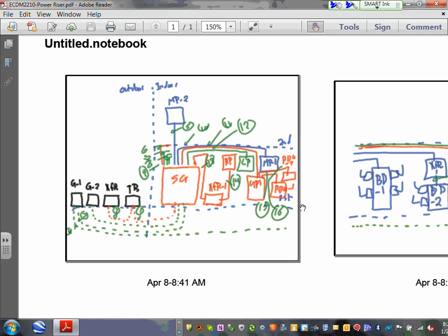How many sections do I need? 3 sections. You need 3 sections, right? Then we have 2 generators coming down from the bottom. Because the generators are big, each gen will take half a section because they are closer to 2500 amp. So now I have another section for the generator, and the utility is going to have a section of its own for the information and its own CTs and the circuit breaker.